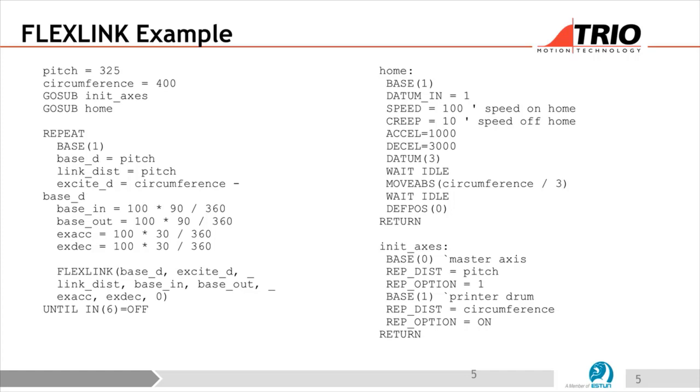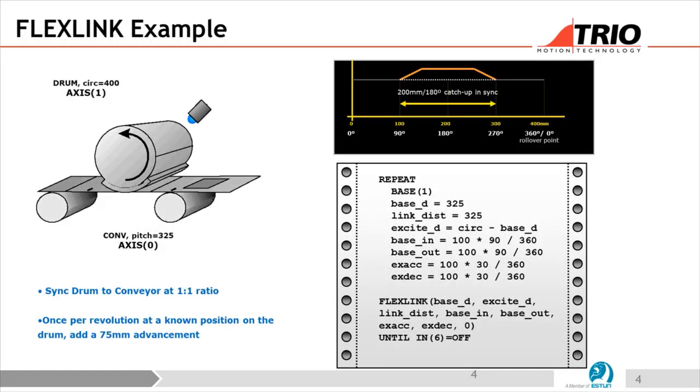In fact, this could take the place of MoveLink in a lot of places. If you remove the base distance, then effectively you end up with a MoveLink. So if I take away the base distance here, so this all becomes 0, then I've got a MoveLink. So it could replace a MoveLink in some circumstances. That reminds me of something about MoveLink: it isn't possible with MoveLink to do what that does.